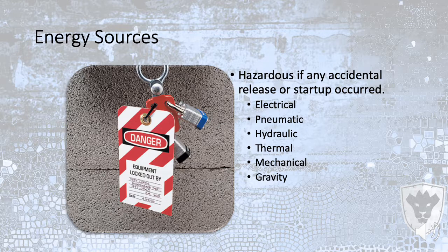Energy sources. Lockout tagout is probably the most misunderstood safety thing. I don't know if it's in the wording or what, but really it's just: is there something that moves electrical, oil, other fluid, equipment? Is there something that moves here? Yes. Okay. Prevent it from moving, and anything else from moving through it, ever again while we're trying to work on it. And everything is a part of that. And then obviously, if you're preventing something from moving for whatever reason, you should communicate that via a tag.